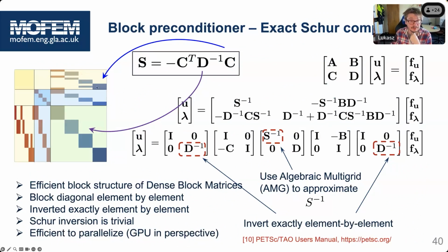So when you want to have zero traction, you have terms over here. But when you have a prescribed displacement, that term becomes zero, and the term on the diagonal appears. Yeah. So when you are in contact, you have terms over here. When you have non-contact, this is zeroed, and these terms appear.